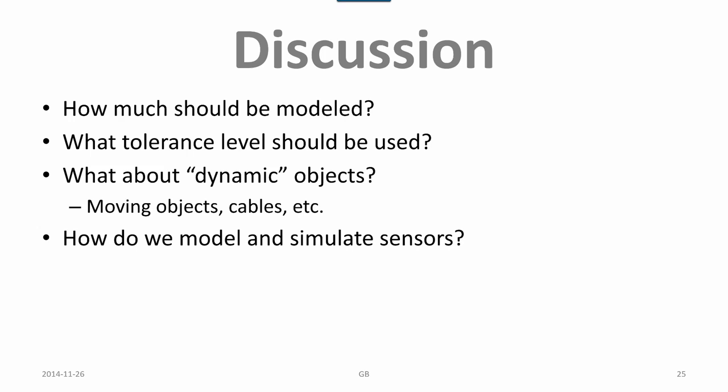In principle, I would say that you shouldn't model more than what is necessary. What is the purpose of the simulation? What is the purpose of the programming effort? In some cases, it could be that we only model things that are close to what the robot is moving around, meaning we have a work table, maybe we have an end effector, we have the work objects, maybe a jig where the objects are placed within, and not much more.